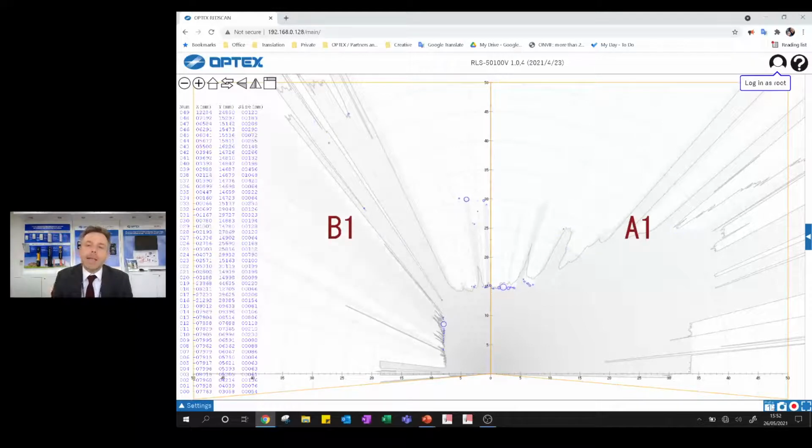What that means is each unit has an input, and that input you can create different profiles, different detection profiles. That's really helpful, say during the day you have a large area that needs to be maintained, but you don't need to go into full alarm should there be an activation, but during the night you need it to go into full alarm. You're able to switch it by using a timer or a security system to give it an input, or access control system. You can switch the detection areas depending on your requirements. So that's a really helpful setting that we have there.